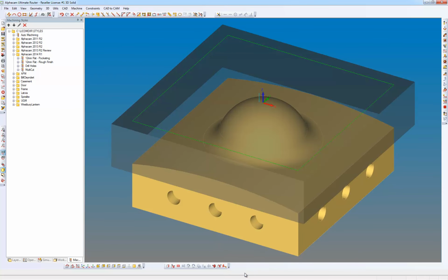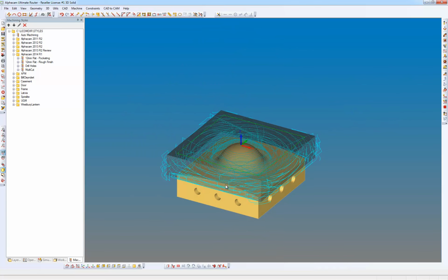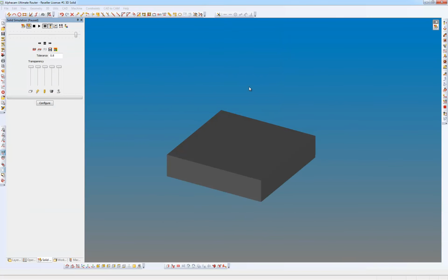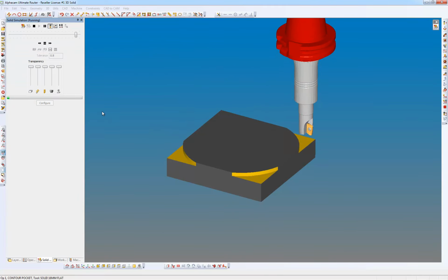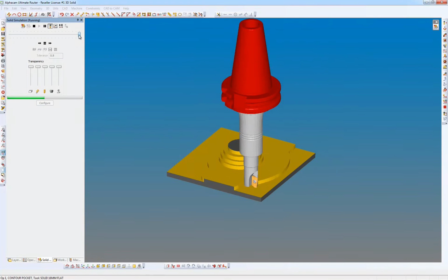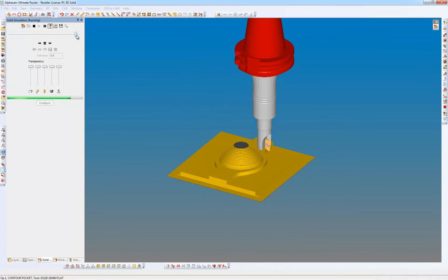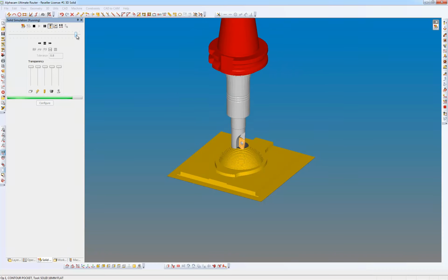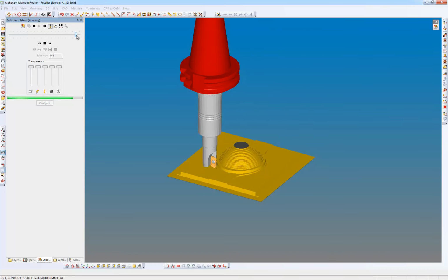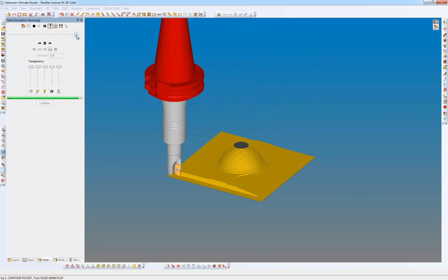machining and then finish, it's created the tool path for me. So if I right click now and do a solid simulation and play, so now we can see our nice solid tool. The solid tools are currently only supported in solid simulation and not in center simulator, and those are the intermediate slices that we talked about. So it's taken 4mm cuts initially, and then it's going back round to take the 1mm off, a little bit like rest machining. So if we come out of here now,